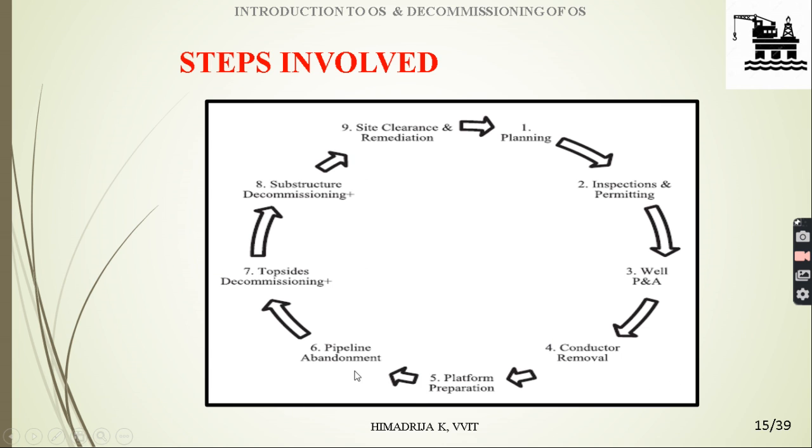So these are the steps involved in decommissioning. As with the construction of offshore structures, decommissioning also involves a huge number of steps, and we need to consider different points for the decommissioning of offshore structures. First, in the planning phase, planning itself starts more than 5 years ahead. There are also many legal procedures. In the planning phase, we consider the lease of the equipment, sales agreement, drilling records, maintenance or inspection records, and any field inspections, all done under this planning stage.